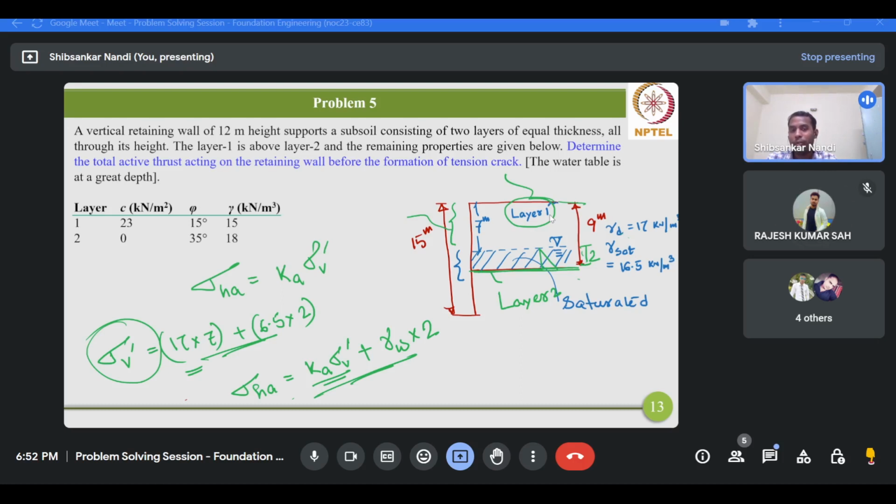It's very straightforward. So the water table location will basically have an impact on the vertical effective stress, or the effective vertical overburden. So your coefficient of earth pressure will only vary as soon as you encounter a different layer. Different layer in the sense that you have different shear strength properties of the soil.